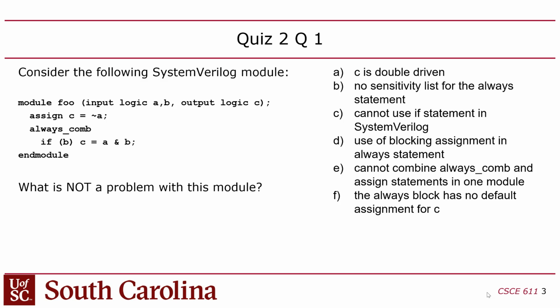In other words, you'll end up with memory in there. And actually, I think the compiler will give you an error, even if you try to compile that, because the compiler will notice that that's a latch. And obviously, that wasn't your intent because you said always_comb. So that's actually an error. So there's actually 4 responses that are correct. It's implied by the question that only one of them is correct, but in fact there's 4 of them that are valid.